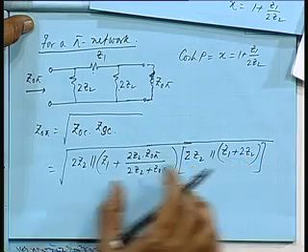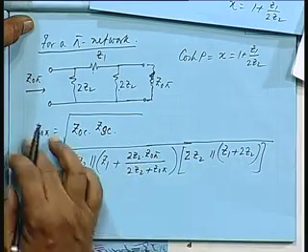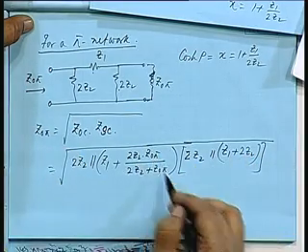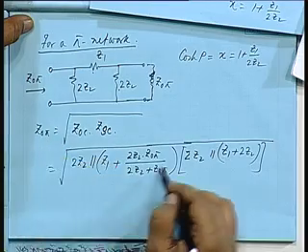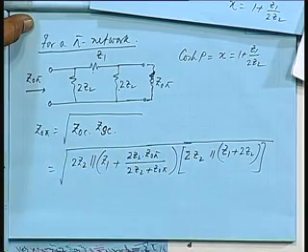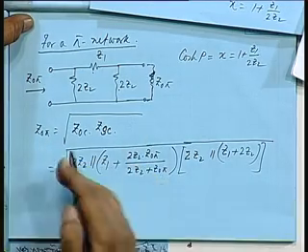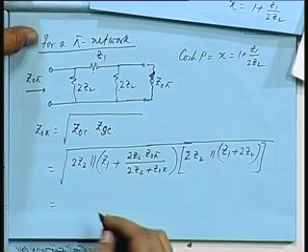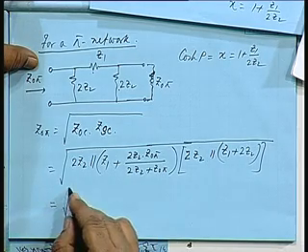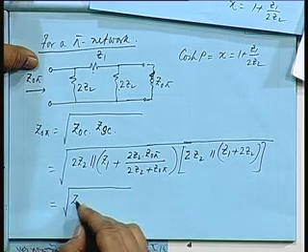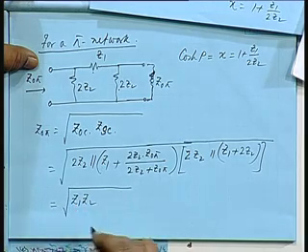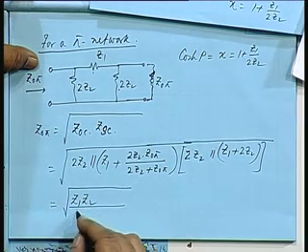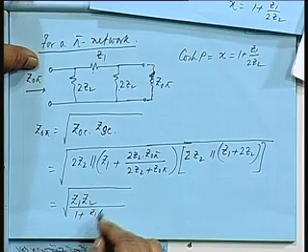Open circuit impedance, short circuit impedance, take the product and evaluate this. Z naught pi, you have to change sides and then make all kinds of manipulations, you can get the result. I leave it to you as an exercise. Finally, you can verify for yourself. This will boil down to a very interesting expression, Z1 Z2 divided by 1 plus Z1 by 4 Z2.